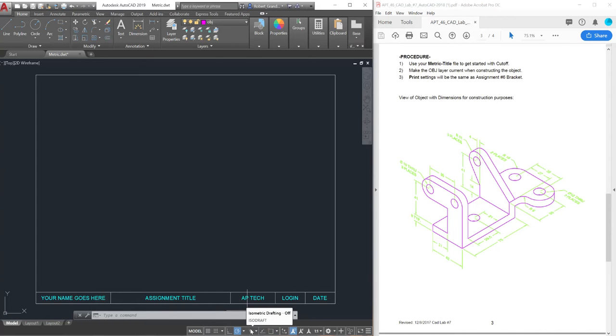And you can see the little cursors down here. If I click on this and then return to my drawing, you'll notice my graphics cursor now has changed the axial directions, and it's showing me a green and red cursor line to indicate direction. So X would be along the red axis, and Y would be along the green axis in this case.